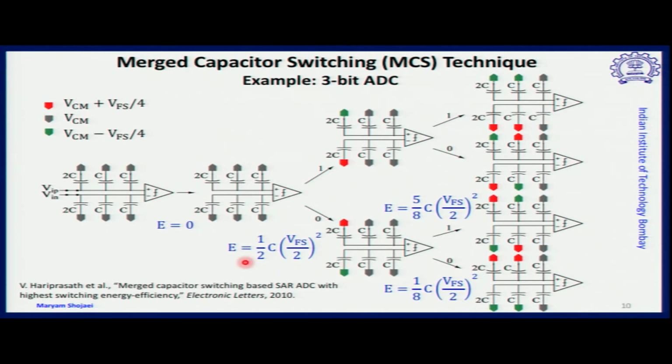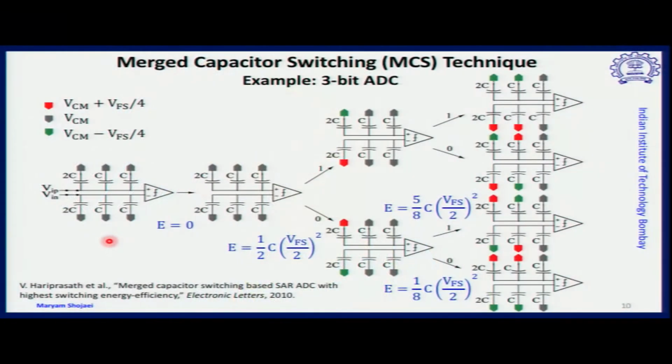Another capacitance switching technique is called the merged capacitor switching, MCS, technique. References for these techniques are provided at the bottom of the slides, so the interested audience may go through the corresponding paper. This technique brings one more reference level into the picture, which is VCM itself. The common mode level also is available and should be available. In fact, initialization is performed with respect to the common mode level, not the actual reference levels for the DAC.